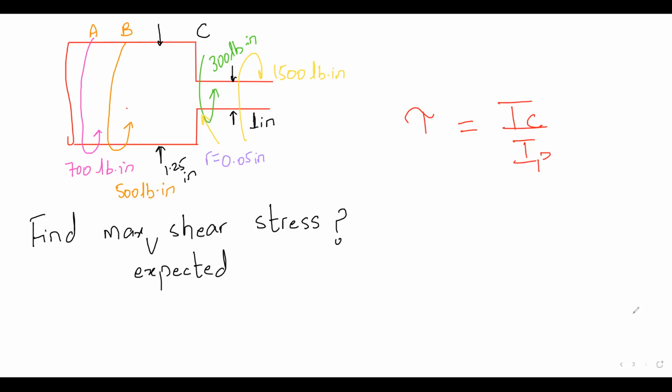So when I have something in RPM, I want to convert it into radian per second. I multiply RPM with 2 pi divided by 60. Okay, and it gives me the answer in radian per second. You don't have any multiplication of r. Okay. Things fine.